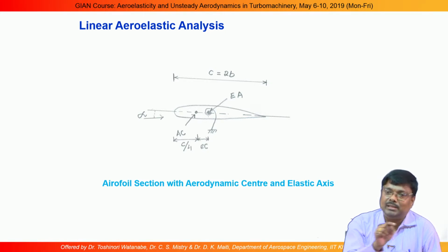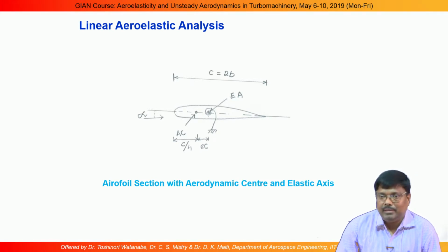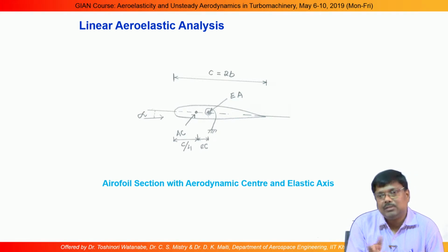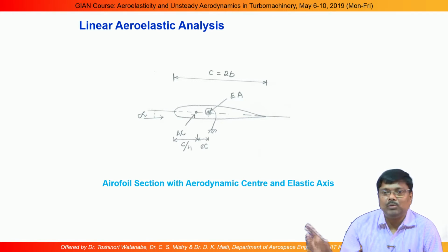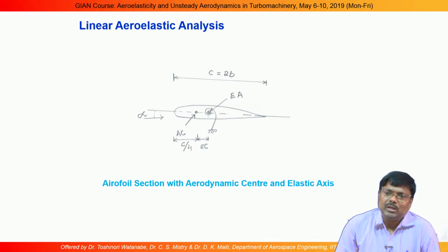Inherently I am considering that the bending stiffness along the chord is infinitely high, so whatever additional rotational angle there is, that is constant for the entire chord length. Wherever you measure, it will be the same. It is an idealistic design, because when we start the design, we have to start with a very simple thing.